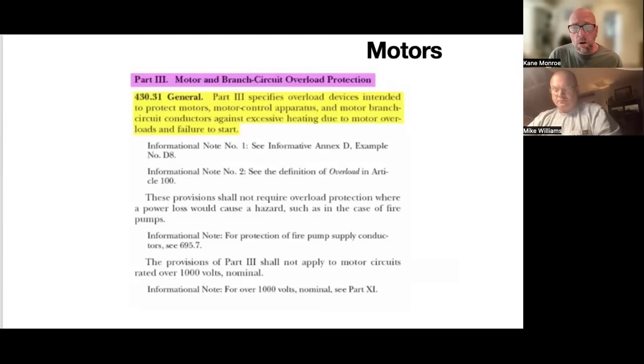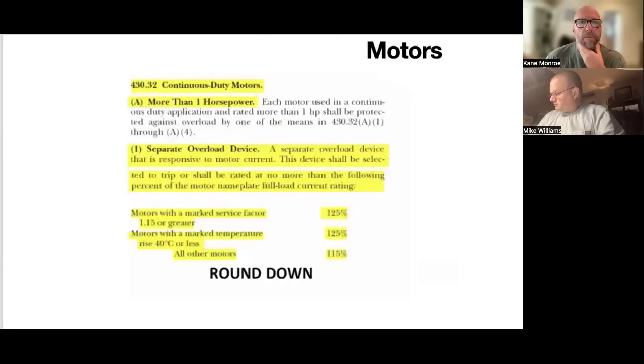Now your overcurrent protection is your breaker, or your fuse, and it's a quick ground fault. It's going to happen quick. So your overload is your heaters, your overload protection. And I'll show you there's a specific way to figure that setting out, and that's usually a test question here.